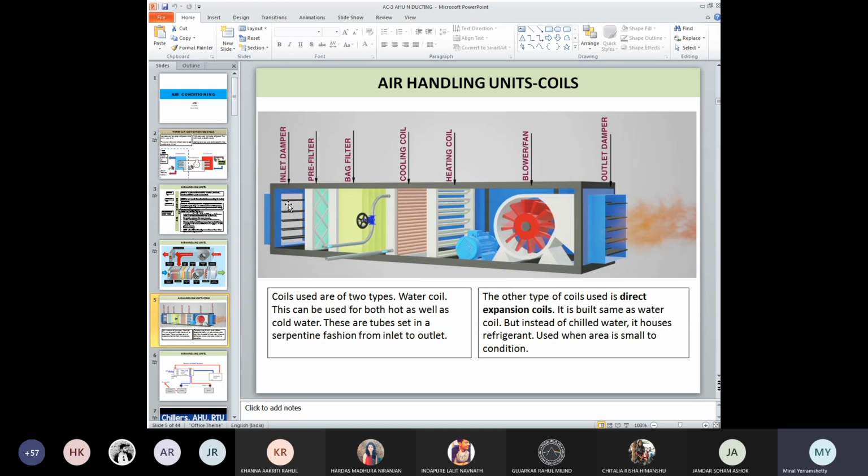Generally, as we keep saying to you, all MEP rooms are basically the prime source of fire, है ना? That means the chances of fire occurring here are 75% more than within a normal room, because of high electrical stationary and mechanical moving parts, which constantly operate, and anything can go wrong anytime. So if fire occurs there, what is the first concern? Basically, the smoke should not go out.